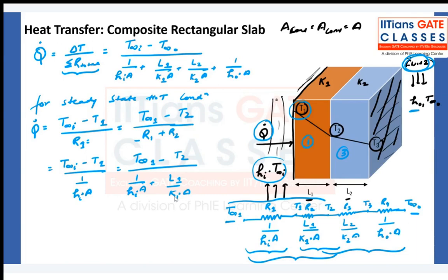No, the heat transfer is the same because we are saying it is steady state. The rate of heat transfer is the same. It is not changing anywhere. We have assumed three assumptions. First, it is a steady state. The second is there is no internal heat generation.